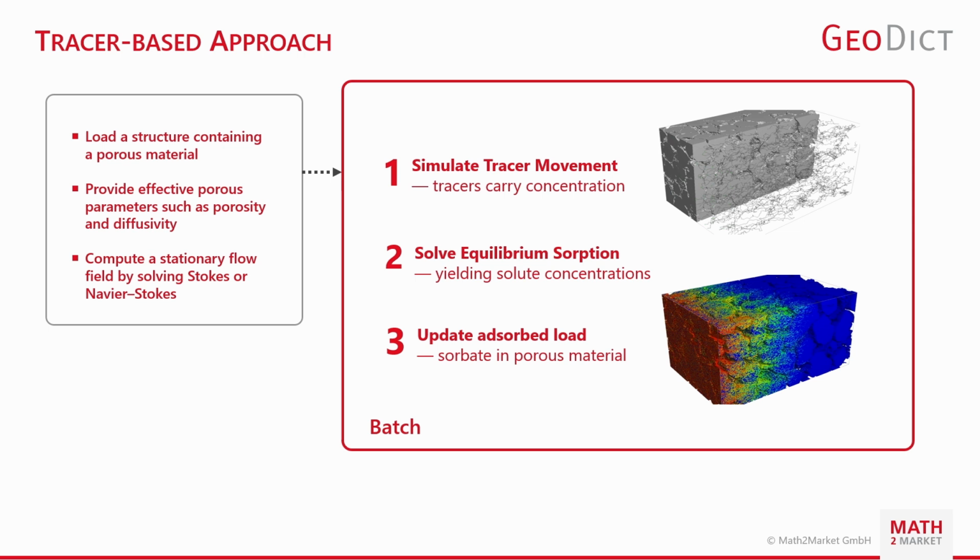As we recommend the tracer-based approach, that's what I'm going to tell you more about. So first of all, we're going to load a structure containing a porous material. That's exactly what we did. You can also, if you already have the product, if you already have a prototype and a micro CT scan, you can also just import the scans and then have your 3D model in the software.